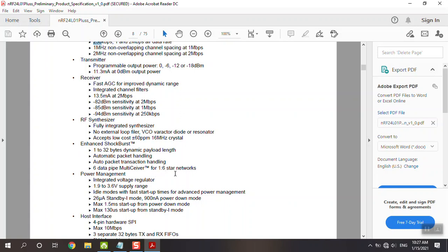This means when we transmit data between the transmitter and receiver, in this module we have 6 pipes. A pipe is like a way where the transmitter and receiver go, stand there and talk, or for example send data on the same pipe. I mean the address of the pipe in the two projects, in the receiver and transmitter, must be the same.